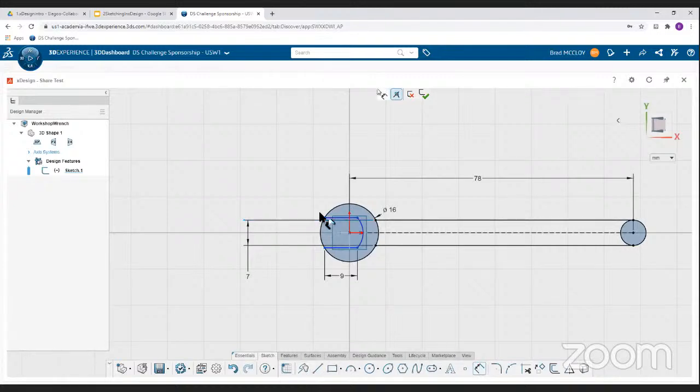So we're going to do, I think I said a 9 millimeter wrench. Click between there and there, and say we want it to be 9. Okay, so we're getting close. This line isn't defined yet, so let's click on this guy. Okay, there. Oh, so we kind of just defined it. So yeah, if you ever do something you don't mean to, click on the line. You can hit the delete key.